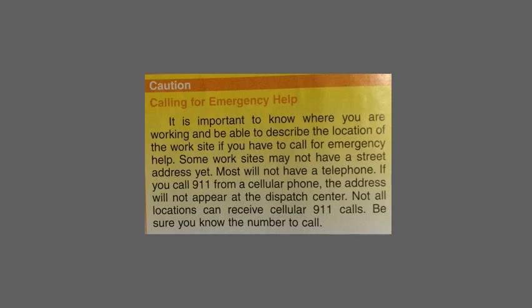Always wear your safety glasses whenever there is the slightest chance of an object being projected. You should also wear safety glasses when working in a position that causes you to look overhead. Dust and debris often fall from upper areas during construction. If any of this material falls on your eye, you may suffer an injury ranging from eye irritation to a scratched eye, or worse.